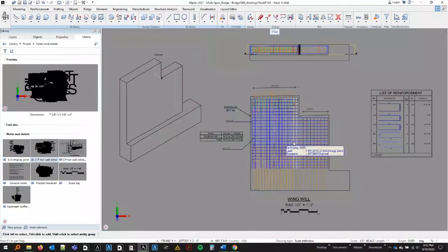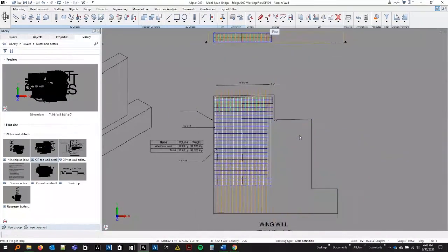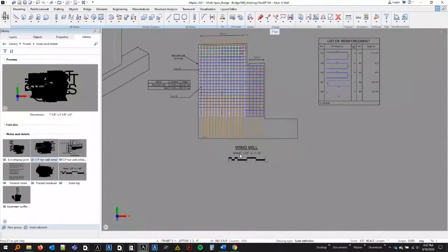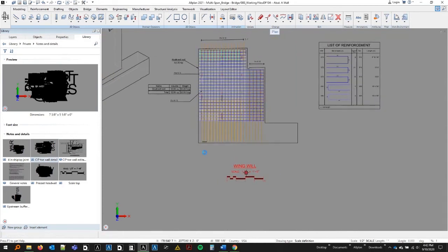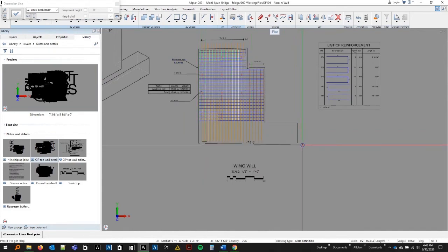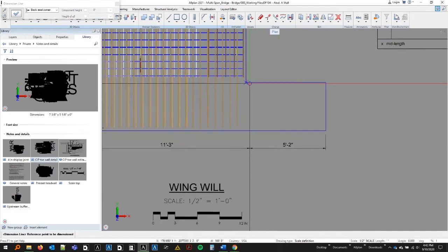You'll notice down here that my, oh, I forgot to do one thing actually, I'm going to undo. I forgot to do a dimension, so let me place a dimension line real quick. And I'm going to move this text down. And I'll start my dimension tool. These are associative. So when I click on points, you'll notice it's actually selecting the 3D object. So it's going to lock onto that 3D position, even though I'm placing a 2D element here.